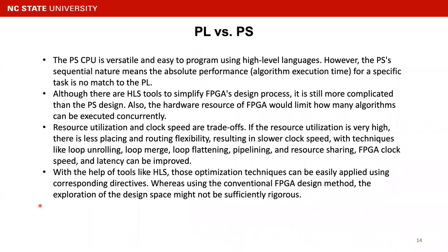As we mentioned, here's a comparison between the PL and PS. The PS CPU is versatile and easy to program using a high-level language. However, the PS sequential nature means the absolute performance, i.e. the algorithm execution time for a specific task, is no match to the PL.